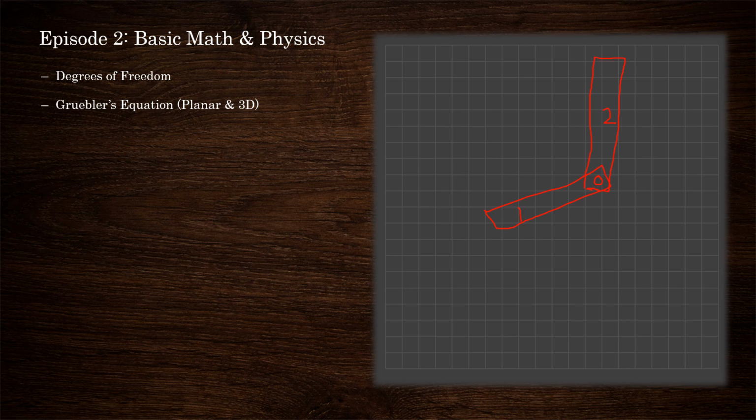Object 2, by being constrained with object 1, has lost its ability to move in X independently and move in Y independently. All it can do is just rotate about a pivot. So 2 degrees of freedom have been lost for one of the objects.